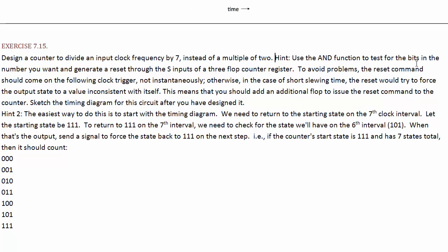Well, the hint is to use AND functions and test for the bits in the number you want, and generate a reset through the S inputs of a 3-flop counter register. To avoid problems, the reset command should come on the following clock trigger, not instantaneously. Otherwise, in the case of short slewing time, the reset would try to force the output state to a value inconsistent with itself, so that's no good. This means that you should add an additional flop to issue a reset command to the counter. Sketch the timing diagram for the circuit after you've designed it.